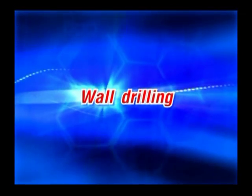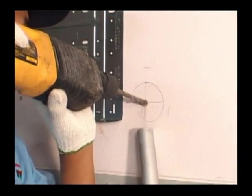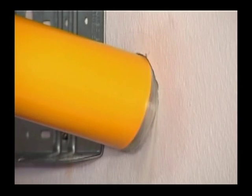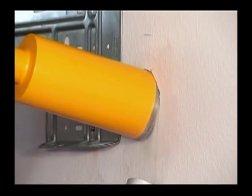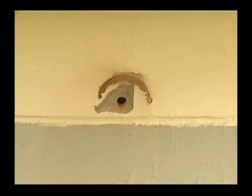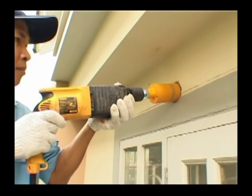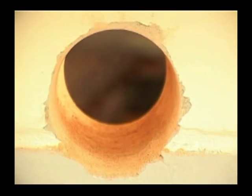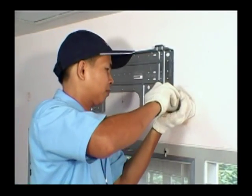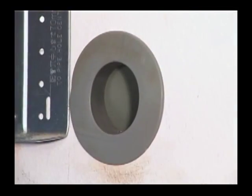Wall drilling. Apply an electric drill to drill a hole at the wall from the inside to the outside of the room. The hole must be sloped down by 5 degrees to facilitate water drainage. As the drill nearly penetrates the wall, stop and then drill the hole from the outside to prevent cracks on the outside surface of the wall. When the hole is bored, cut a plastic hole sleeve and insert it into the hole.